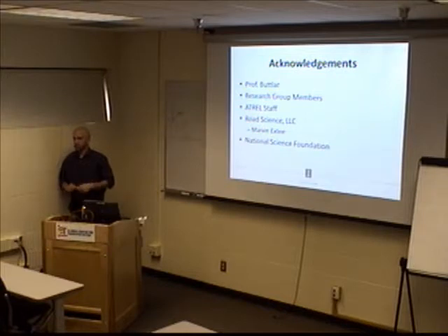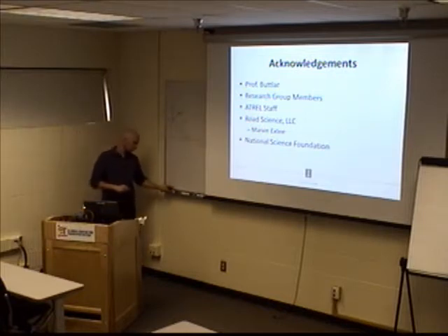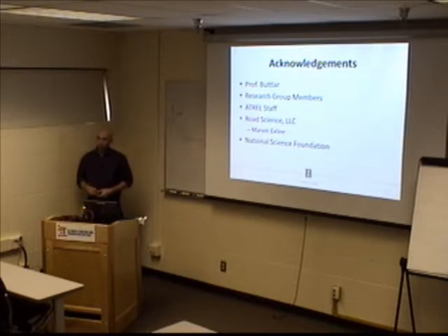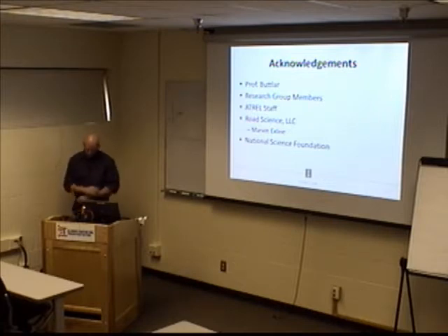One of the really surprising things we found when we started testing binder: I was a little skeptical when Salman did some of the first large-scale binder tests because I thought we'd run out of binder. For one thing, it uses 100 times more binder than the conventional Superpave test, but luckily we had a good supply on hand. So we started doing DCT and IDT binder fracture tests, obviously at low temperatures.